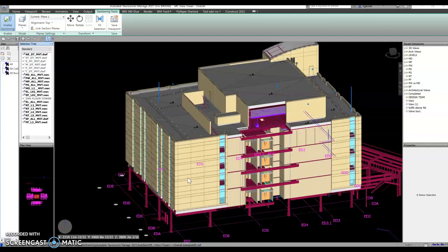Today I'm going to be discussing how to set up a project that you want to coordinate with BIM. For instance, here on my screen is a 6-story hospital that I've started the coordination on. And it's pretty important to get your project set up the right way with all the models aligned and accurate so that you can run proper and accurate clashes on them.